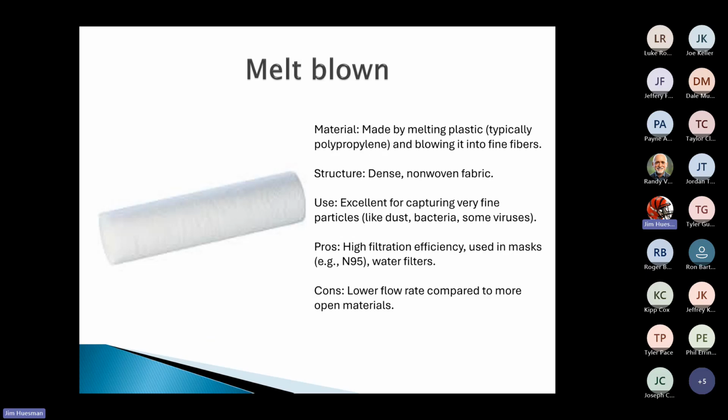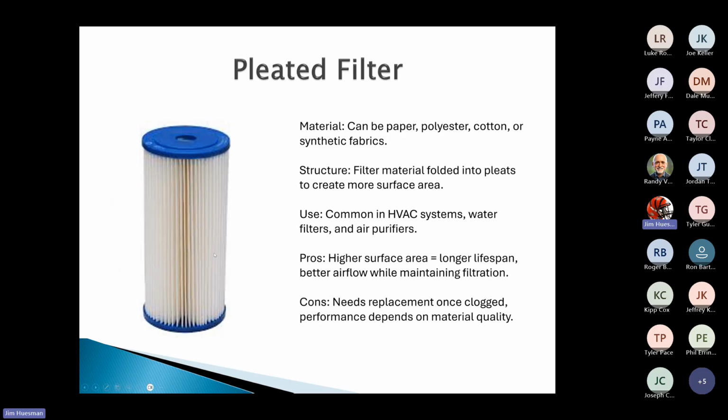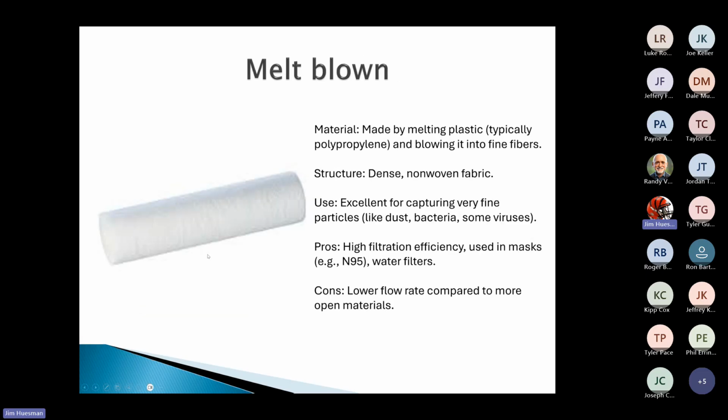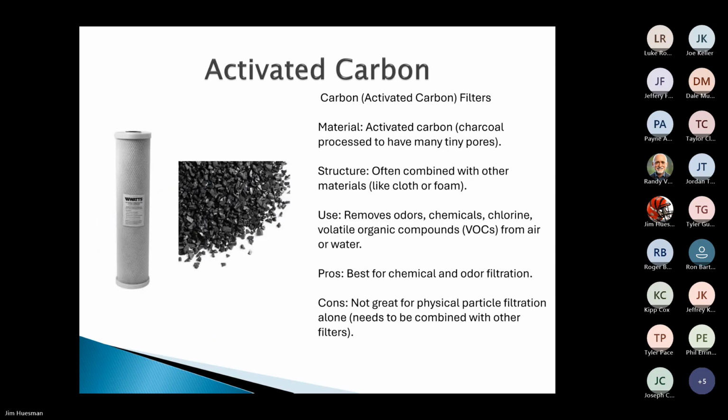We'll talk a little bit about it, but when we talk about pleated filters, we'll be jumping into microns, all right? And when we talk about the melt blown, we'll talk about microns, and that's basically measuring the size of the holes, or how that water is going to be passing through it. Again, great, but it's very tight. It will fill up quick, and based on your water quality, if we're doing a melt blown, you're going to need more of a preventive maintenance program. You're going to need to change that out more. It does a lot more than a pleated, but it also clogs up a lot quicker.